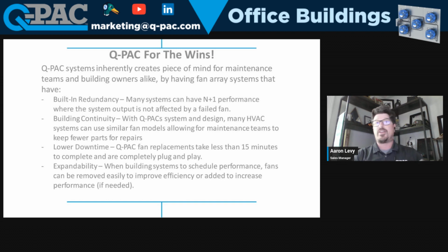If for whatever reason they needed more capacity, or they say, well, we think it's 30, but it could be 40, we would do the reverse. We can make a wall that has slots for 8 fans, only ship 6, and then if they ever need to expand that system to 7 or 8, they can just add fans, plug and play. All the wiring harnesses are still there. And so they have the option to design a system bigger than they need to with the expandability of potential. One of the big options, and one of the stories, was for a hospital in Florida.